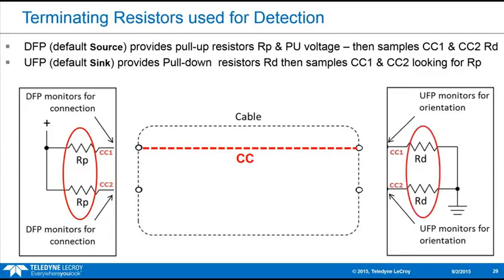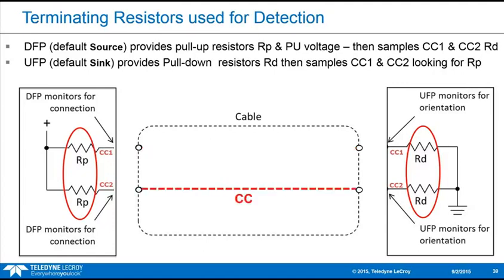So this sink really is on its side. So he takes both CC pins to ground. They only see this termination on the one CC line that's connected, right? So they know this is the line they'll use for PD communications. So now they have to route the other signals I'm not showing accordingly.